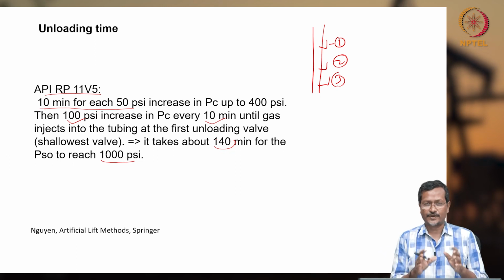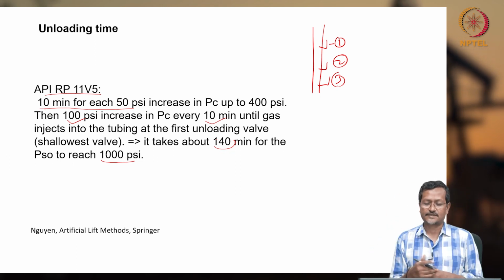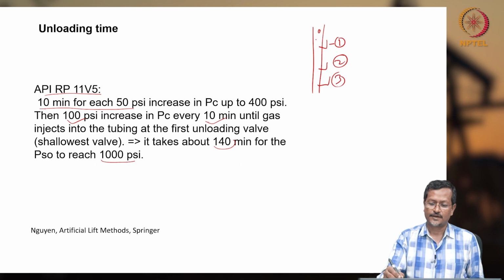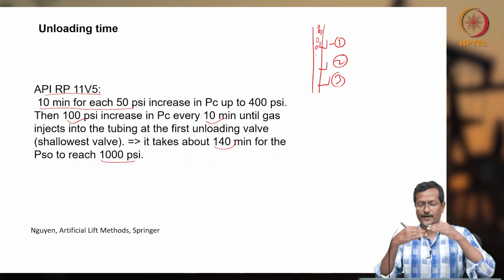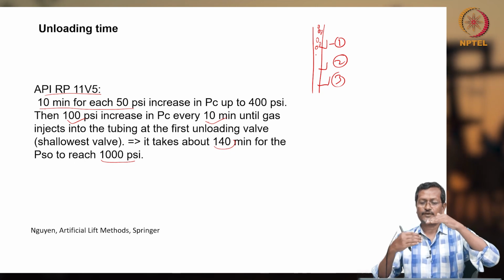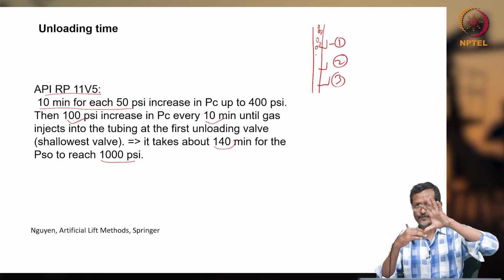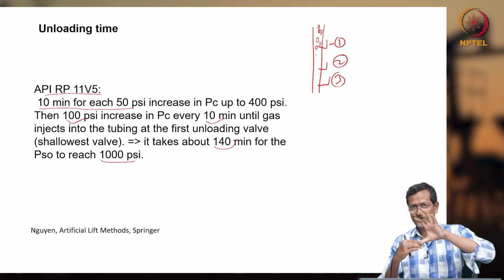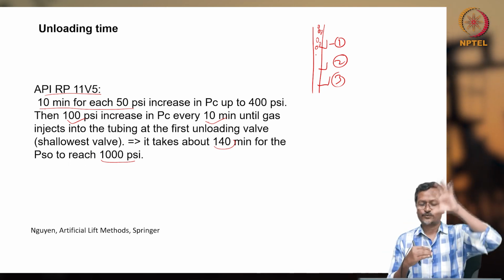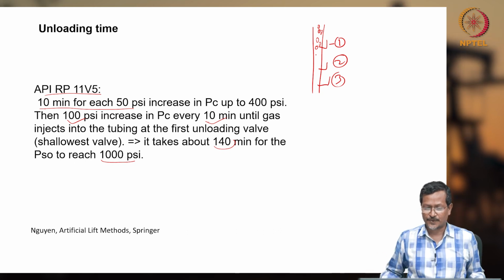So you have to give a certain time so that fluid gets stabilized in the tubing and bubbles will be formed. Hydrostatic pressure will be reduced. Again you activate the next one, again you reduce further hydrostatic pressure, you give certain time to be stabilized, again the next one, again the next one, again the next one. In that way you reduce the hydrostatic pressure.